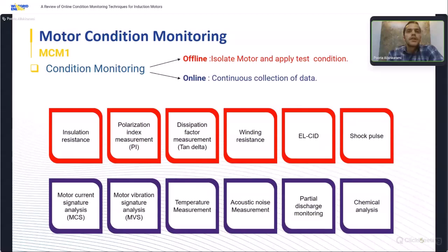Or, for example, consider the chemical analysis of the bearing grease, also called oil analysis. This method involves periodically extracting a sample of the bearing grease or journal oil for laboratory analysis. This chemical analysis can reveal several fault conditions, for example, identifying metal particles or detecting ingress of water, dirt, or process chemicals, or lubrication degradation.